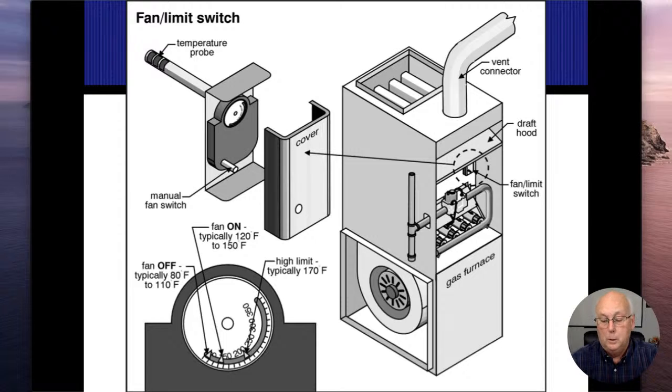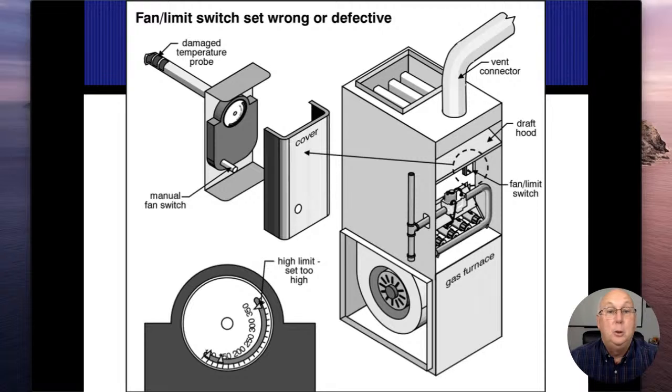Okay. So fan on, 140. Fan off, 100. Furnace shutdown, 200 is a nice easy number to remember. All right. You can adjust that.